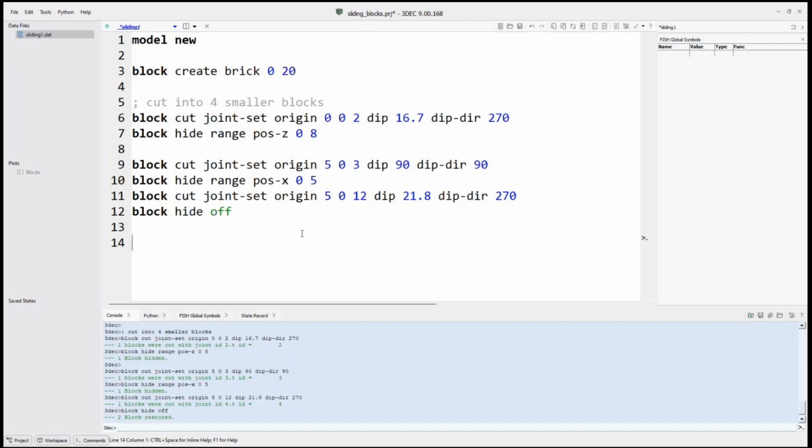This is a rigid block analysis. In 3DEC, it is possible to create blocks that are deformable, in which case you need to give them a stiffness, like a Young's modulus. You could theoretically give them a strength, like a Mohr-Coulomb material. They can potentially fail. They will have zones inside of them, so it's like a small continuum model within each block.